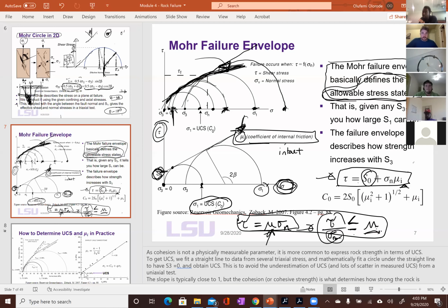Our focus will be, okay, we already know the definition of effective stress. As we begin to increase pore pressure or decrease pore pressure, what happens to the rock? Does it begin to slide? And that's actually what we have. That is called induced seismicity. We are injecting fluid into the rock, and all of a sudden we start to see earthquakes because we have decreased effective stress up to the point where you are now equal to this value, and you create sliding. That's the moral of the story when we get there. Good.